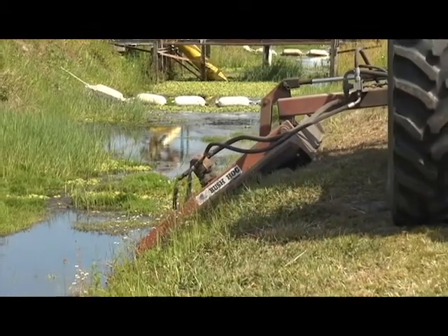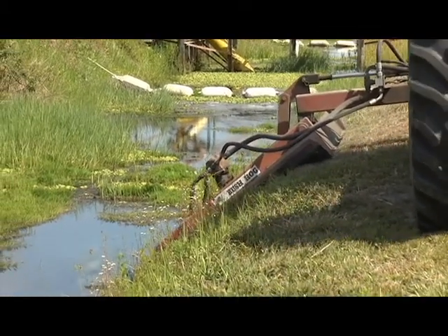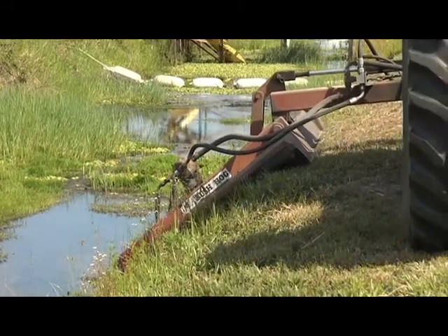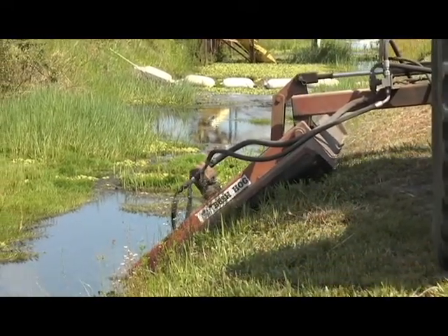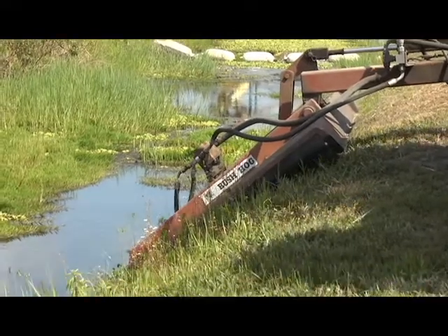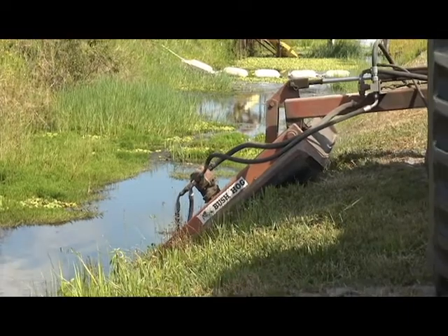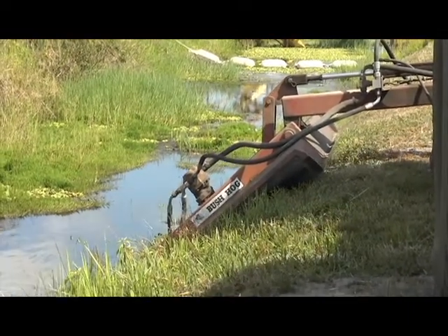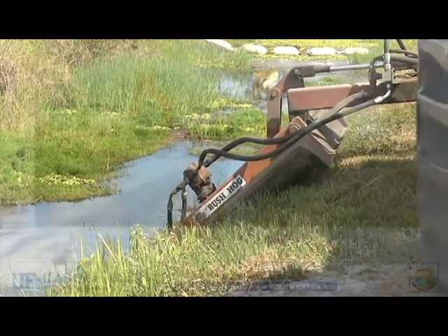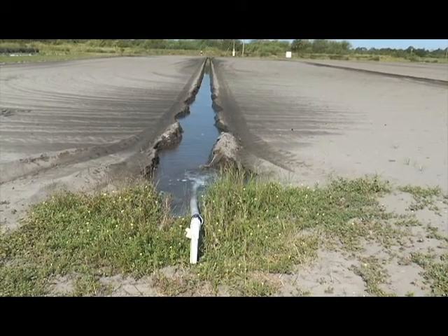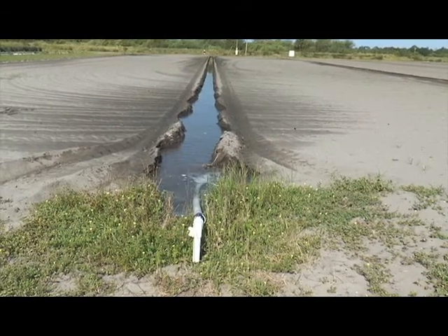There are many factors that influence the flow of water in open ditches. One of the most important of these is the cleanliness of the ditch. Weeds and debris, if allowed to accumulate in open ditches, will decrease their capacity. Grass and weeds may also grow in open ditches to such an extent as to reduce the capacity of ditches to less than half. It is important to routinely dredge ditches to maintain open ditches. Small open ditches are usually constructed with a V-ditcher.